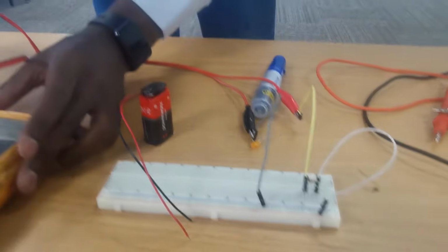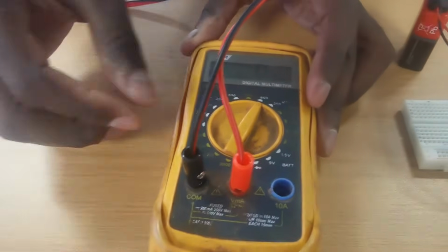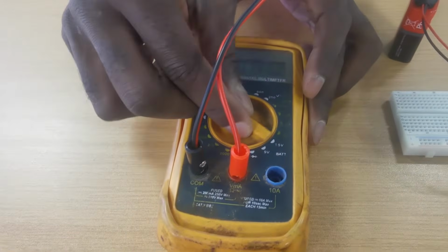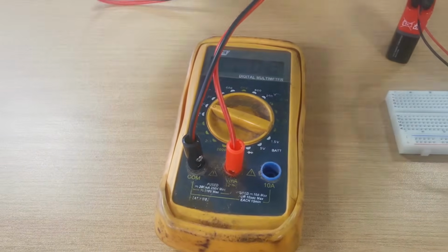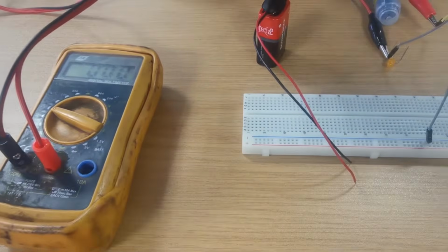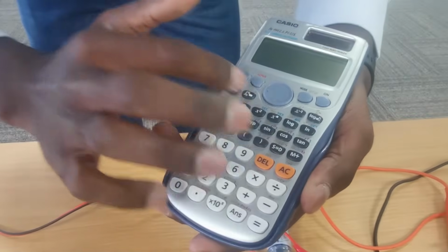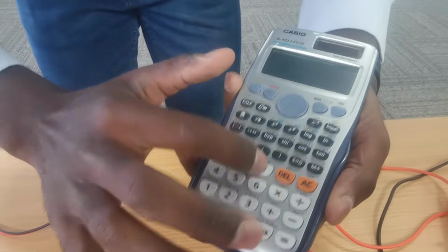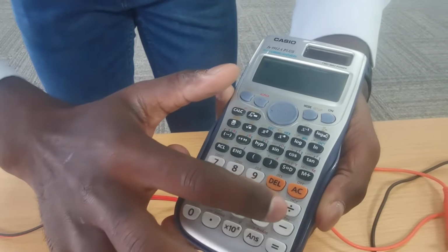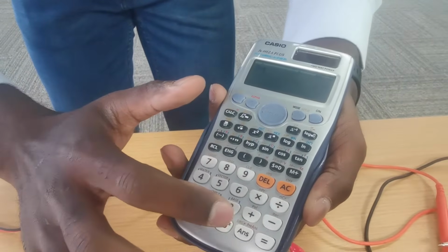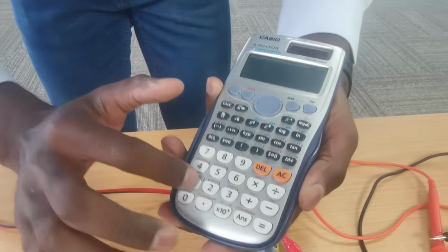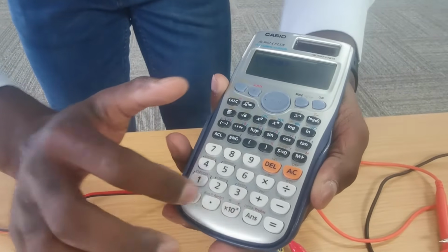Okay, make sure that my ammeter is sitting on a particular range. How do I know which voltage, or which current rather? Well, I've got a 9-volt source that is divided by a 10 kilo ohm resistance.